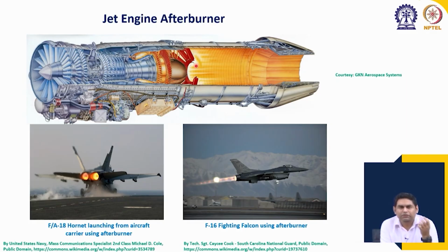Why do they remain in the combustion products? Because gas turbines have combustion at very lean conditions, meaning a very large amount of excess air is used to keep the temperature low. So, here that extra air is used along with extra fuel which is injected for secondary combustion. This process is known as afterburning, and the advantage of this is that because there are no moving parts, no rotating parts after this, we can take the temperature to very high temperature here, which was not possible in the combustion chamber due to the presence of the turbine.